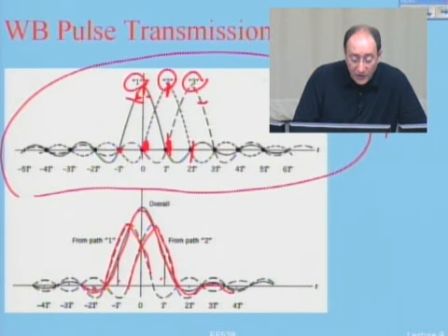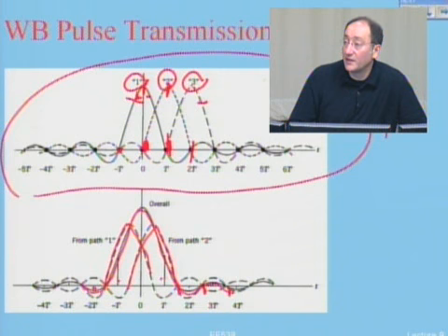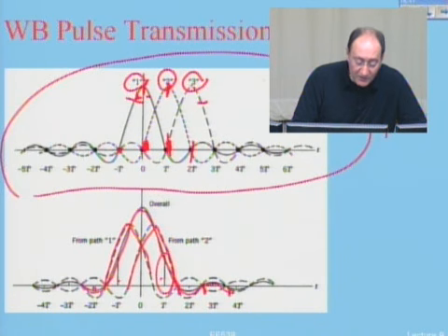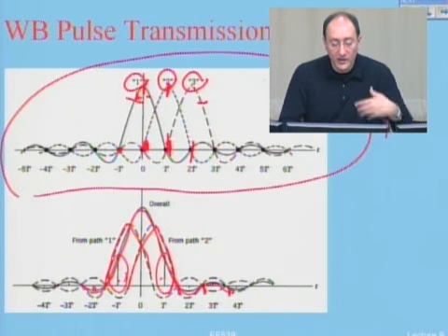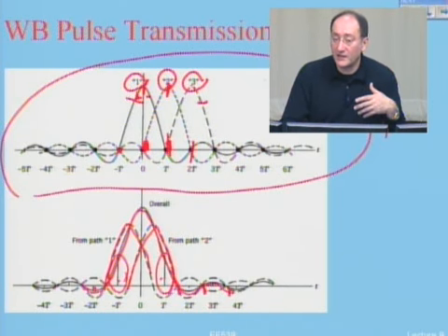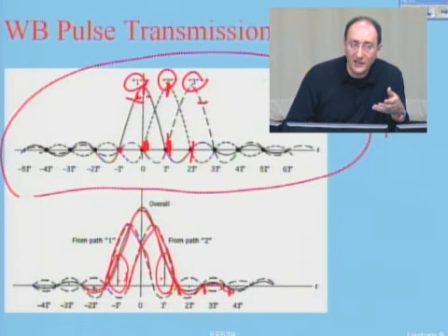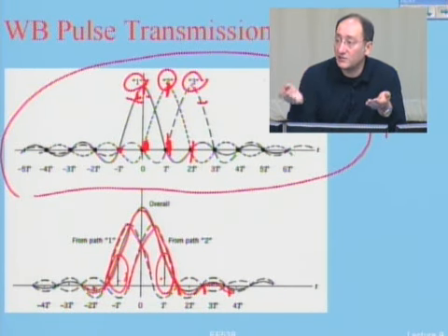And this overall received pulse may not be necessarily 0 anymore at this sampling time. Since it is not 0 necessarily at the sampling times, what will happen is that I will have intersymbol interference. For example, I have this much intersymbol interference. Do you follow me? The raised cosine pulses are designed so that they are 0 at T, 2T, 3T, etc. If I increase my data rate, now the paths are coming away from one another. They are no more 0 at T, 2T, 3T, etc.